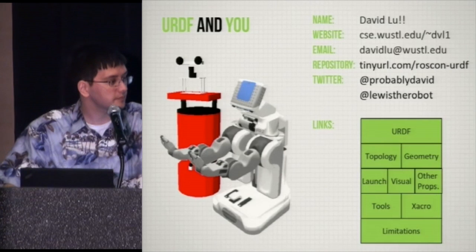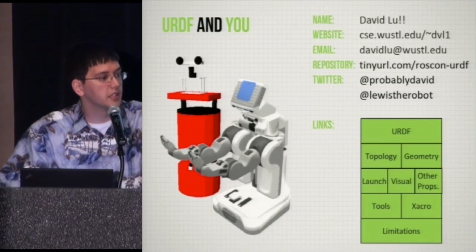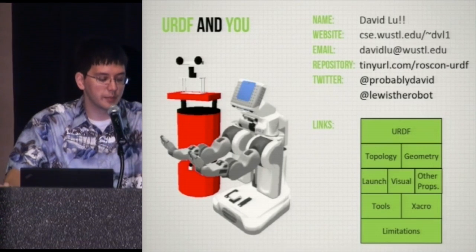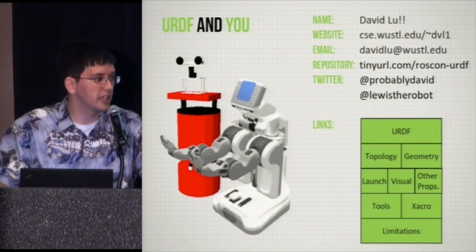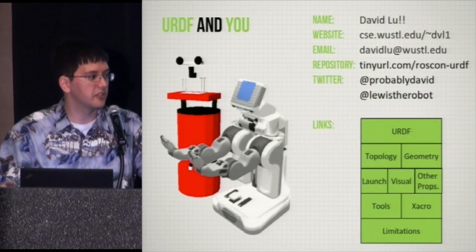Yes? So clarifying on Xacro, that's pre-processed data with URDF. Yes, that's pre-processed. And so you don't gain any actual performance upgrades when you actually use it in your code, because what's actually loaded into the parameter server is the full URDF that's outputted from that. So it is pre-processed.